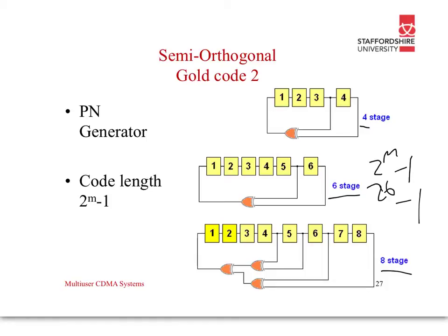We can see that the outputs are the last one and the penultimate one. For the 8 stages, we have 4 feedback stages. Now, you have to look in literature because to get this optimal length code, you can't just pick a random number of feedback stages.